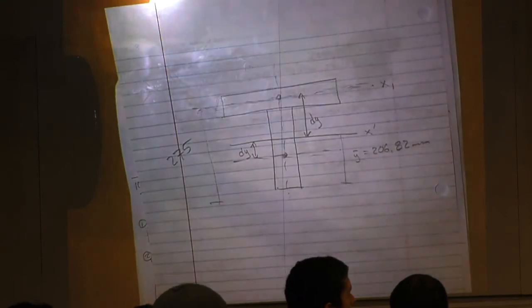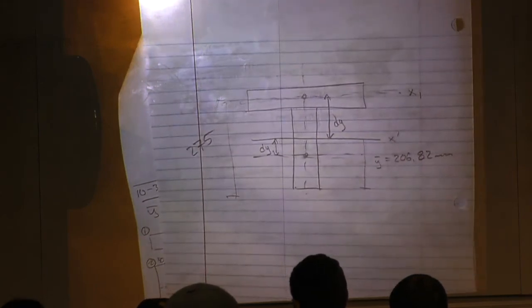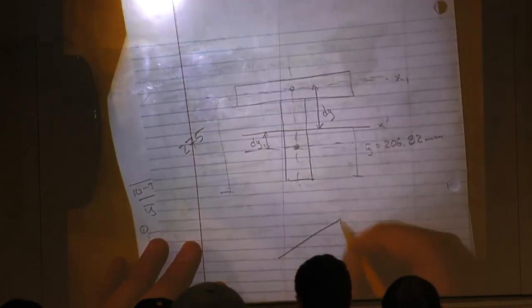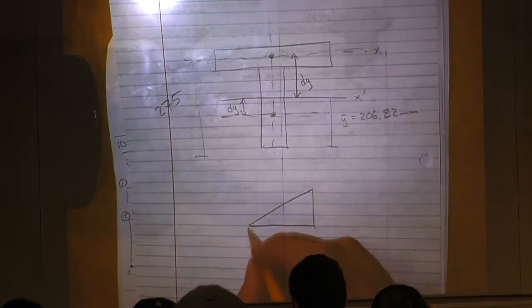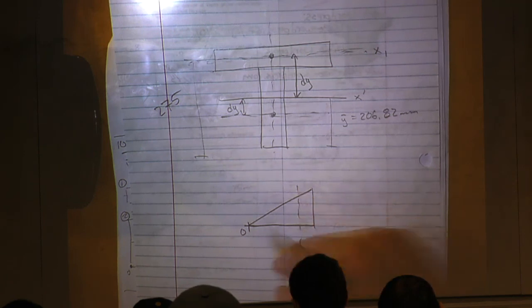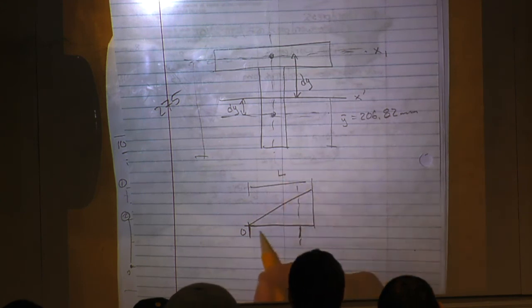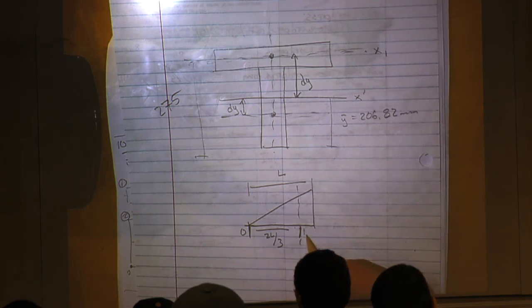Yeah. Question about distributed loads. Okay. Triangles. Sure. So when you find the force, is it 2/3 from the point you're observing, or is it 1/3? Okay. So the question was about distributed loads, but it can also be answered here. It's about triangles, right? So if this is my origin point, then trial and error or equations will tell me that my centroid is located at, let's say that's my total length, this right here will be 2L over 3. So from the small side to the large side will be 2L over 3. This will be L over 3, from here to here.